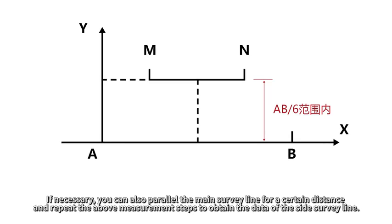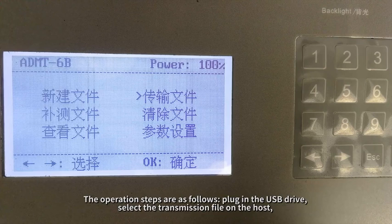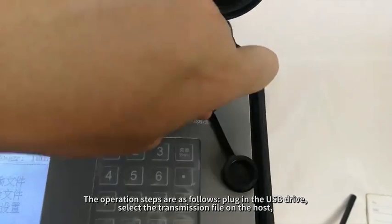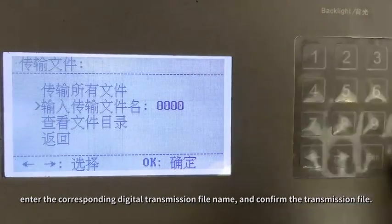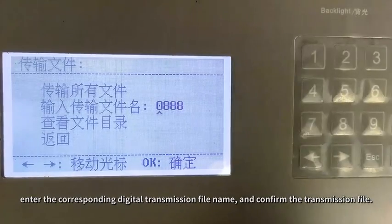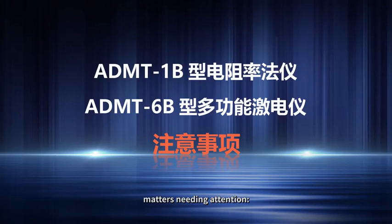If necessary, you can also parallel the main survey line for a certain distance and repeat the above measurement steps to obtain the data of a side survey line. After completing all survey tasks, export data and draw with professional software to analyze underground conditions. The operation steps are as follows. Plug in the USB drive, select the transmission file on the host, enter the corresponding digital transmission file name, and confirm the transmission file. Matters needing attention.